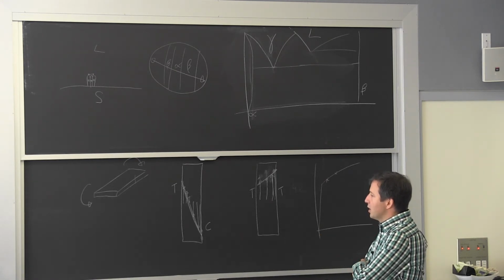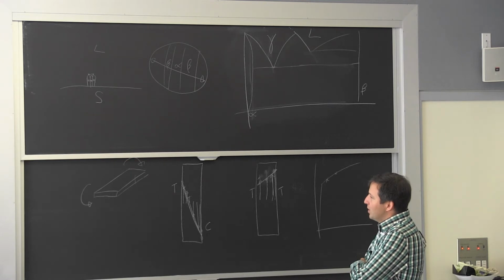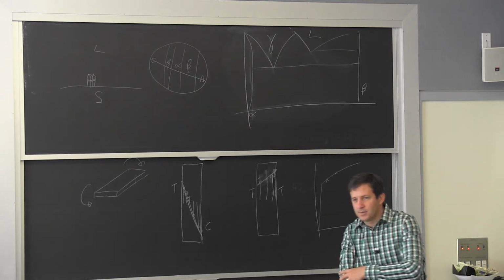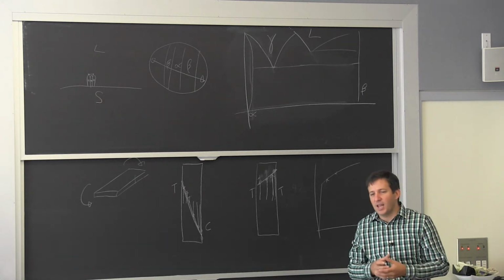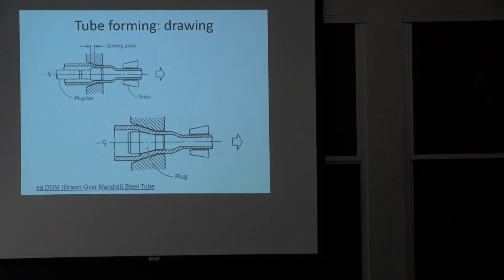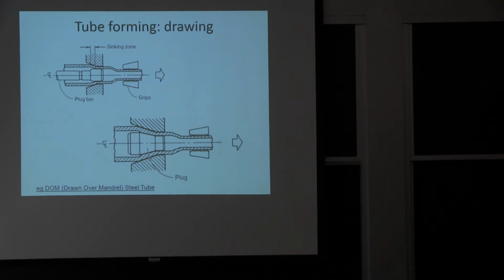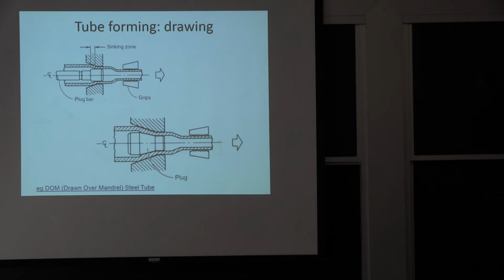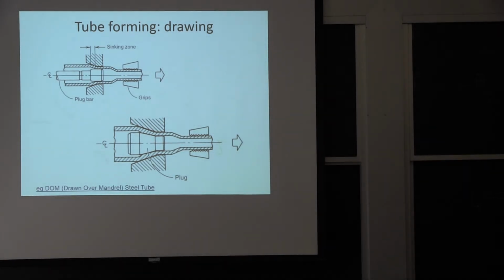We're using a plug or a mandrel to finish a tubing. So you already have something, and with drawing and using the mandrel, you can really control your tolerances very well. If through a prior operation you manage to get the hole, or you form it like we discussed, you keep straining it, and you can do it hot, and that's how you get your diffusion and recrystallization, and you can't tell that it was welded a while back.